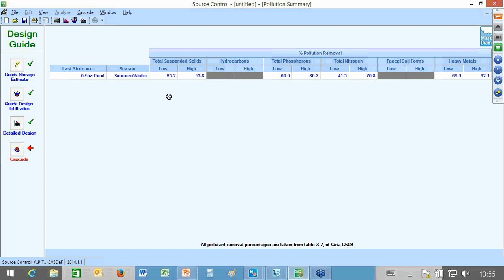Yeah, good questions, folks. The questions coming in are: is there any kind of documentation to enable us to make meaningful choices? There are, and normally when I'm doing this on the training, there's a SUDS planner that comes in with the program. I'll show you that very briefly, but there is an option to use the SUDS planner, and in the SUDS manual there is a lot of good experience which will tell you which are the better options to use. The SUDS planner is based on the original SUDS manual C609.